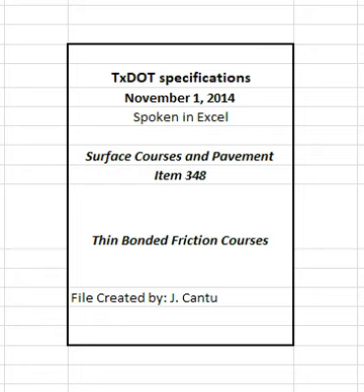4.4.2.1.7 Ignition oven correction factors. Determine the aggregate and asphalt correction factors from the ignition oven in accordance with TxDOT. Note that the asphalt content correction factor takes into account the % fibers in the mixture so that the fibers are excluded from the binder content determination.